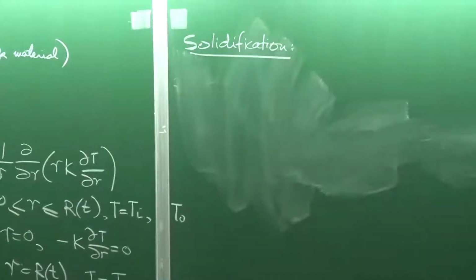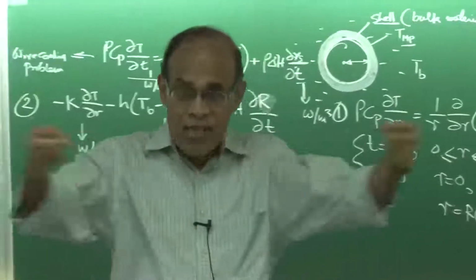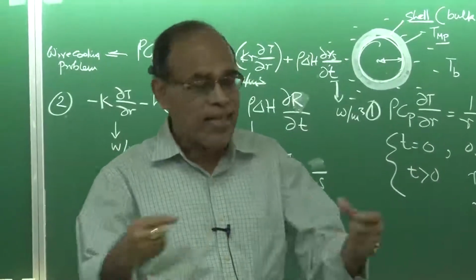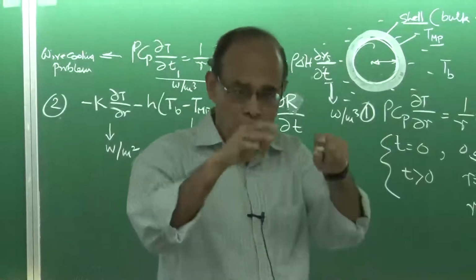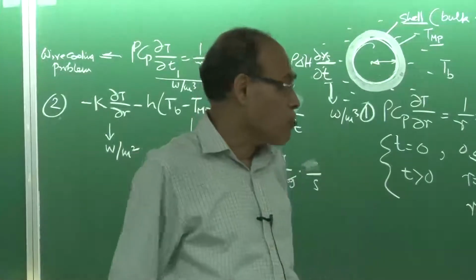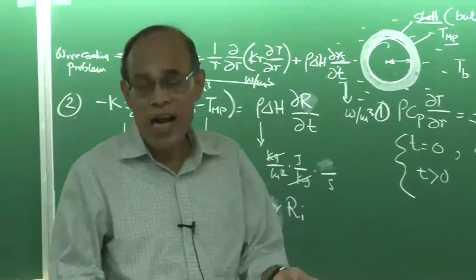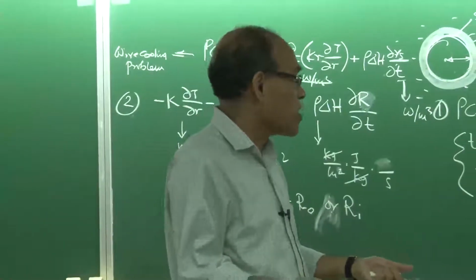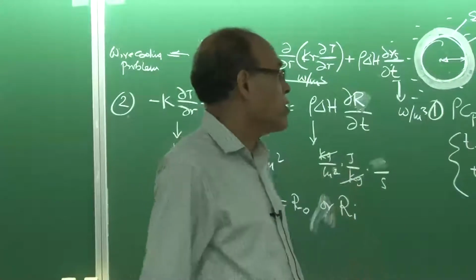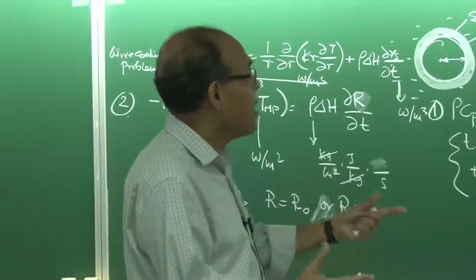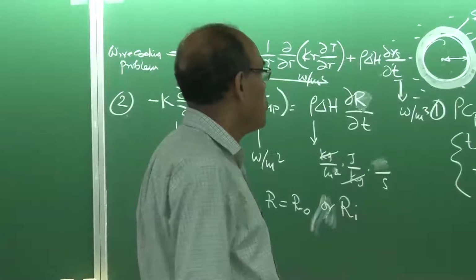Solidification basically, as you all know, involves heat transfer. So we extract heat from the liquid, and as a result the temperature of the liquid goes down, and once it starts to go below the liquidus temperature, then the solid formation starts, and once the solidus temperature is reached, everything becomes solid.